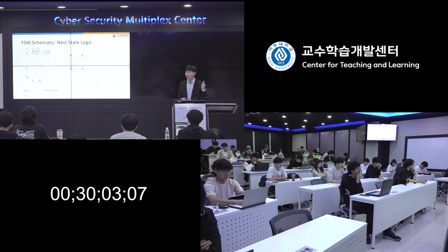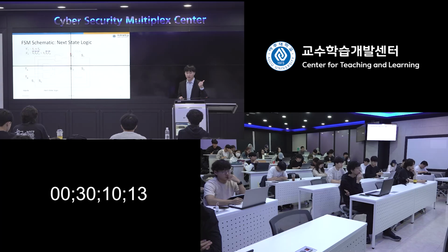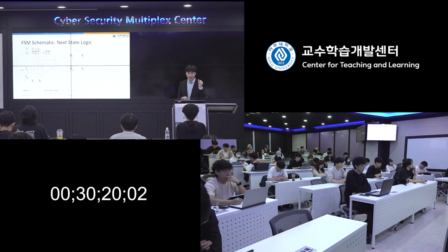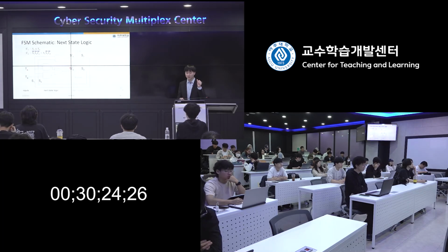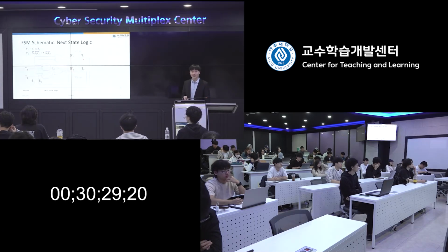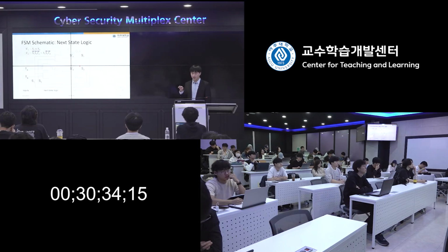So whenever you have a change, an update to this circuit, after some propagation delay, that data will be reflected in the S prime. Let's say immediately, even if it has a very short delay. Once you have an update in TA, TB, S1, S0, it will be reflected in the S prime state immediately, because it doesn't need to wait for the clock rising edge. Keep it in mind because it is important when checking the timing diagram.